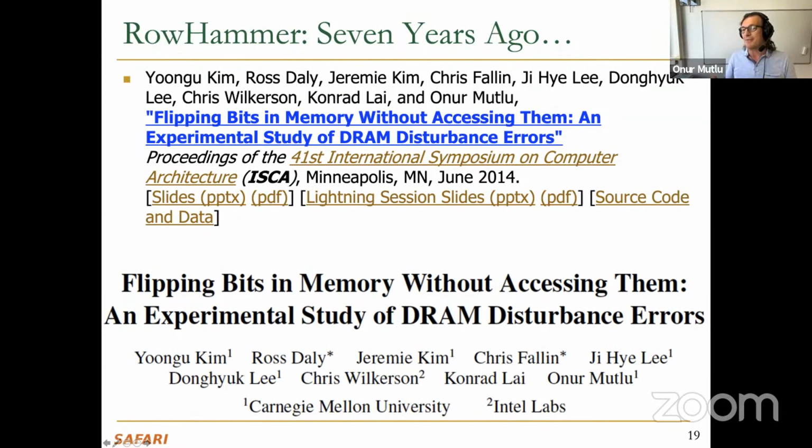Basically, with RowHammer, these disturbance errors started happening through software, meaning you could actually induce these disturbance errors within a refresh interval in DRAM, and there are no other correction mechanisms. As a result, these bit flips directly get exposed to software. Now, that's a huge problem, clearly, because it affects your reliability, it affects your security, and it affects your safety. So hopefully that answers your question.